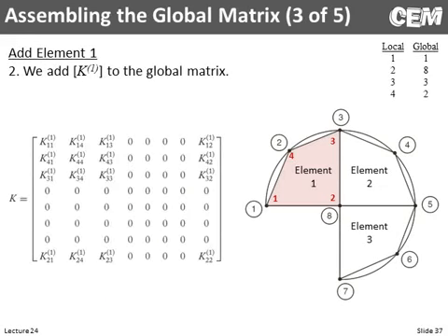So what we're going to do, we're going to take the element matrix for this element, which is a 4 by 4 matrix, and populate the global matrix with it. So remember, local node numbers to global node numbers. We're going to use that. So where does local K11 go? Well, K11 has 2 subscripts being the local node number. It'll go in the 1, 1 position in the global matrix, which is exactly where it is here. It's in the global 1, 1.